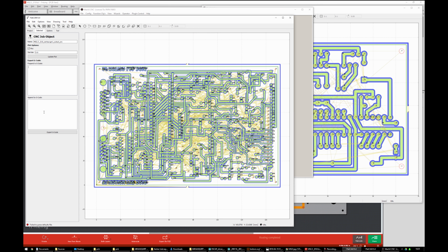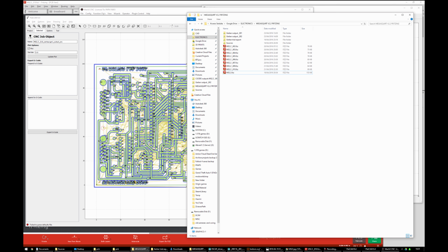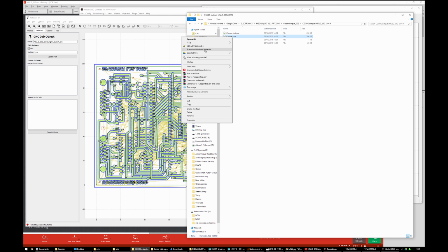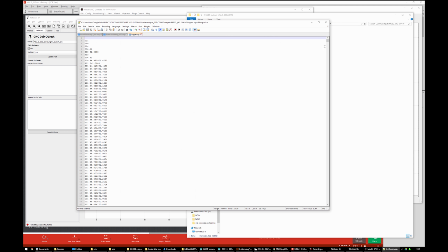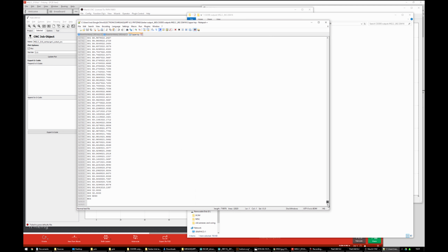So you could put it in here, M99, or you can open the G-code files manually and do it. There's also another thing which it needs, which no one mentions. Well, if you find that the nesting wizard doesn't work, I don't know if you need to delete this or just tag M99 after.